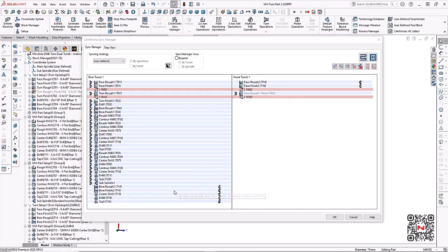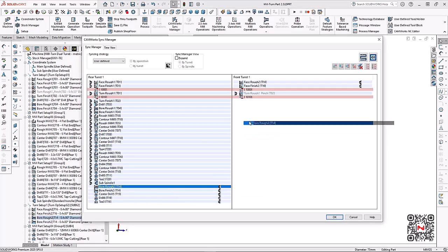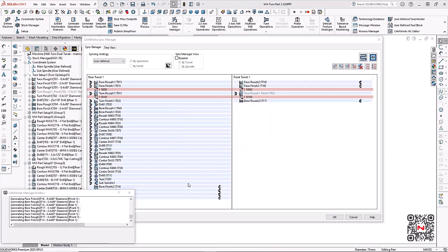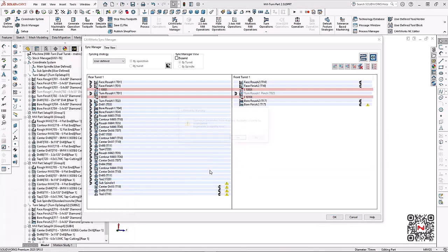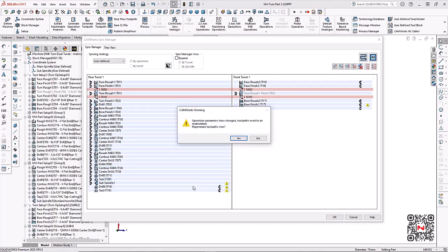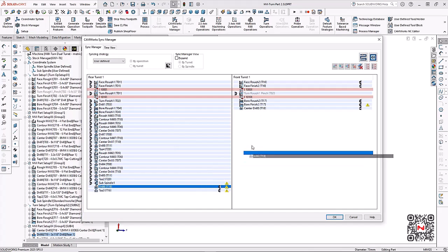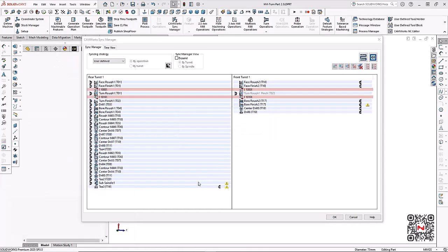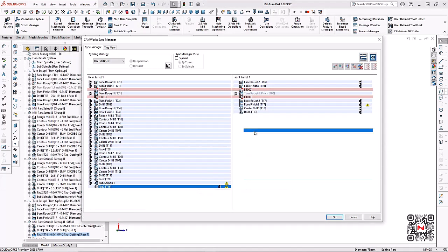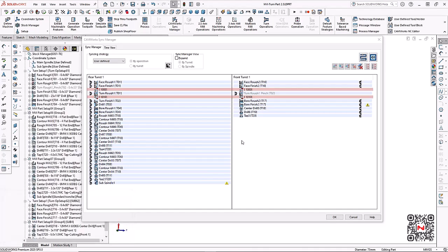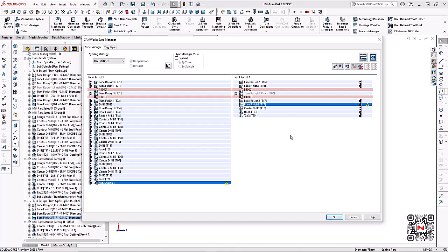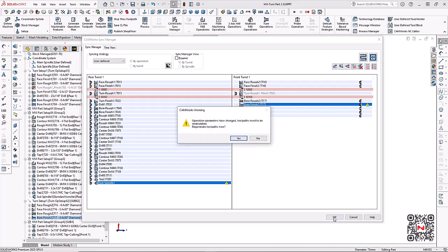And then once that is complete, what I'll do is drag the roughing operation over, as well as the boring finish operation, and then the center drilling, and the drilling, and the tap for the M6 holes that are in the flange. So now that I moved all of the operations for the subspindle over to the front turret, let's go ahead and say OK here.